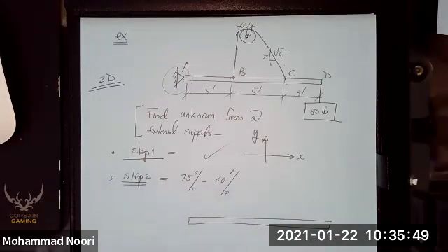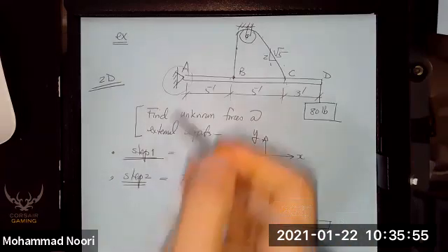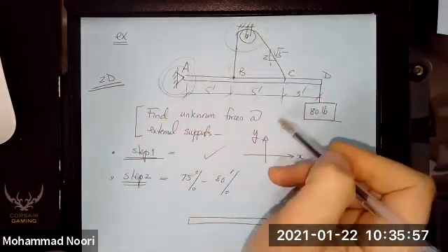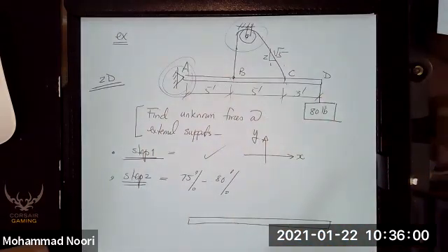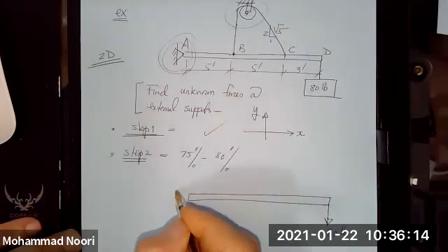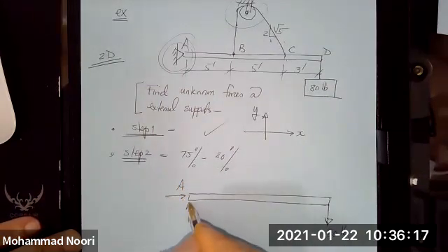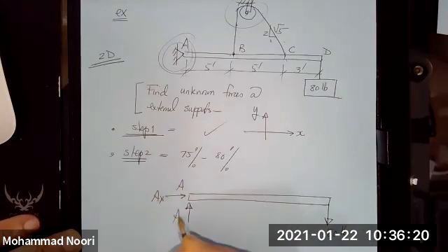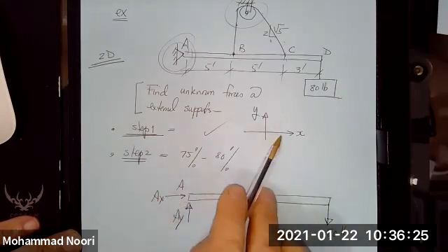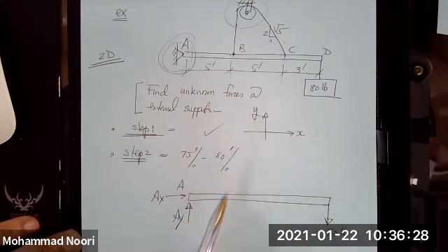That is, you're freeing the object, okay? Then, after you freed the object, you cut these supports, you put back those forces or moments that those supports or external loads represent. External loads are given, that is easy, okay? So what are the forces that this unknown, this support represents? So this is a pin. So it represents two unknown forces that you have, set up in these directions, X and Y.